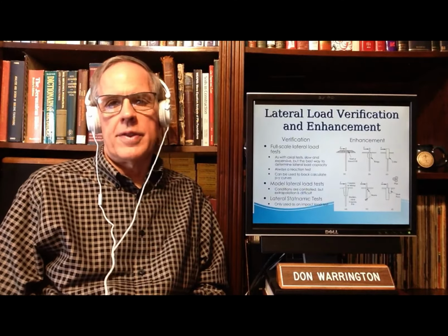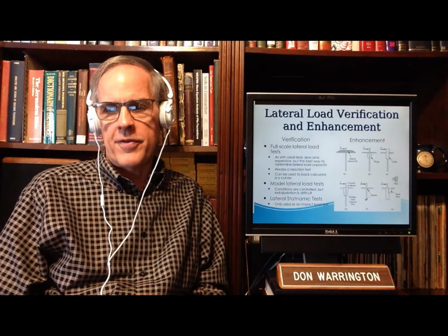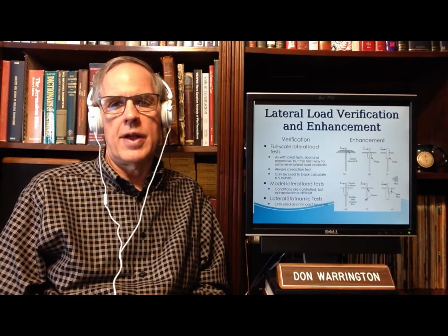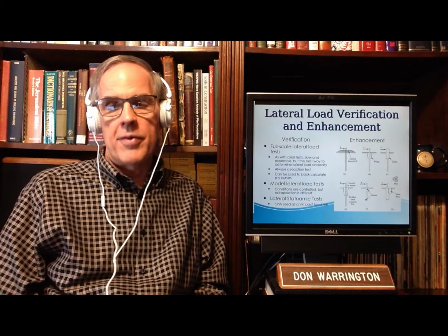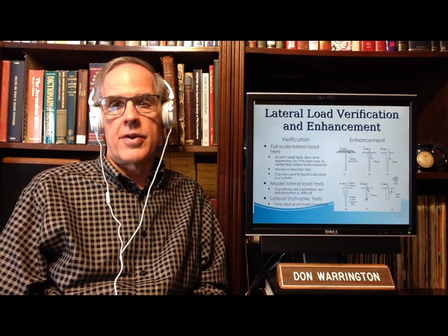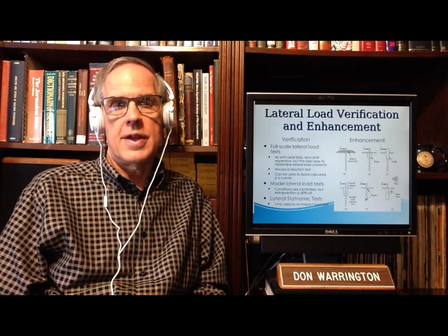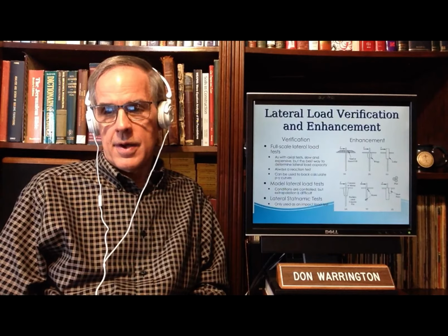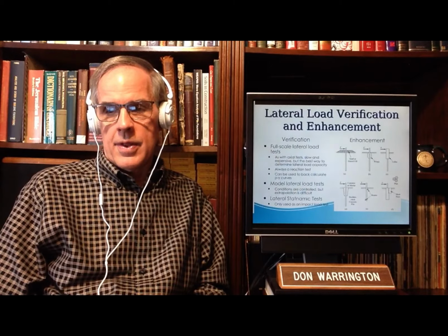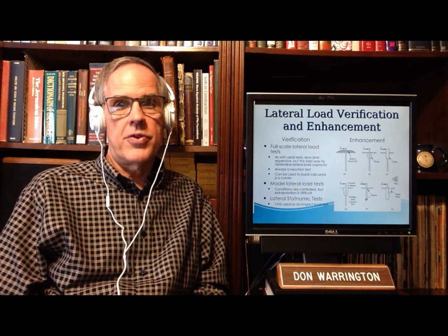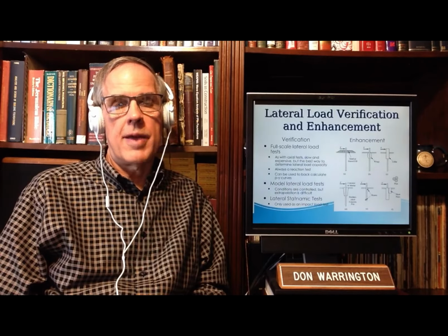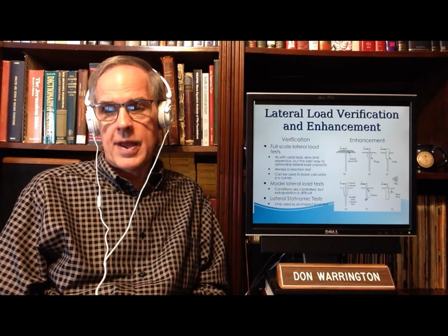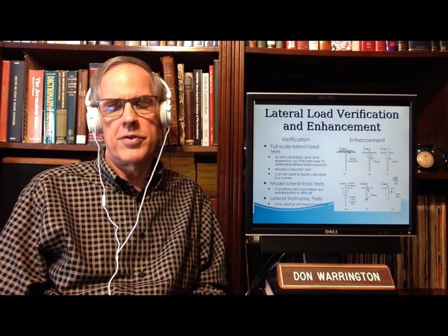How do I deal with lateral? Well, how do I verify it, and how would I increase it? Obviously, there are full-scale lateral load tests, just like there are for axial, and we'll talk about the axial test mostly when we get to that subject. They can also be used, and they were certainly used by Lymon Reese and Mike O'Neill, to calculate p-y curves, although they used a little more instrumentation than that.